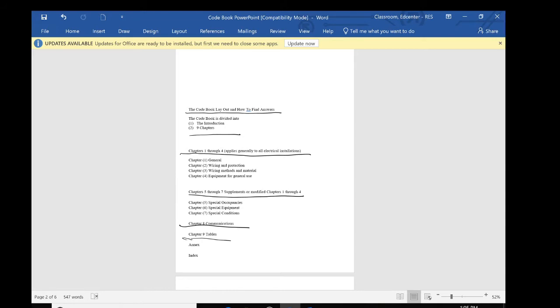It shows you if you have conductors all the same size. So if you have 4/0 wires, you can look and see how many 4/0 you can put in a 2-inch PVC or whatever, but it has all these broken down, so that's done for you. And that's Annex C.